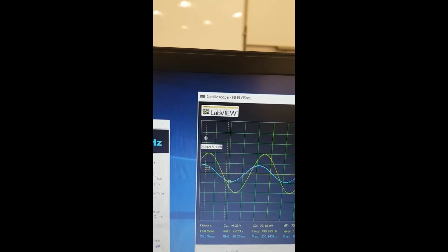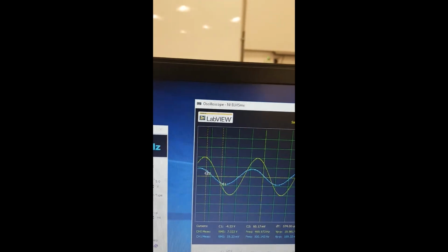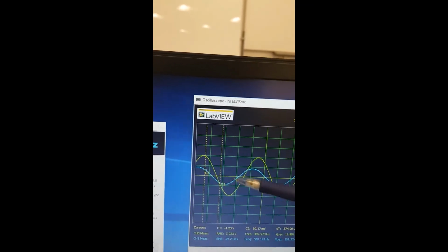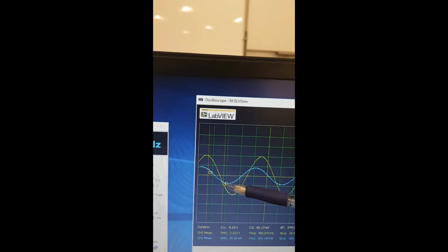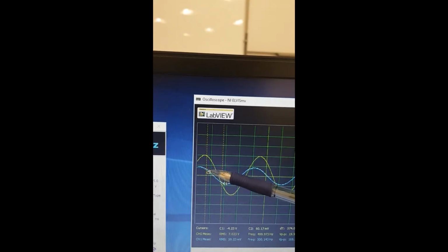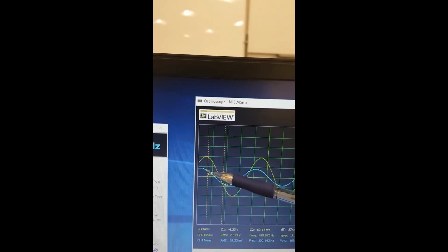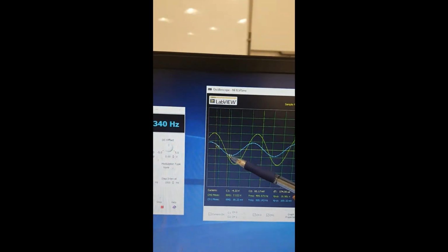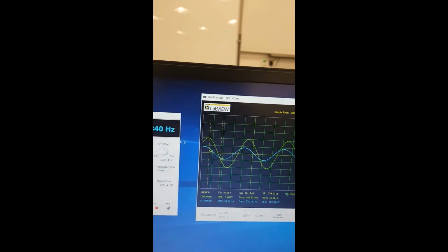Okay, here for C1 and C2, the two cursors, we have a small horizontal line. This small line will be set on the point that we need to read, okay? C1 is always tracking the green signal.